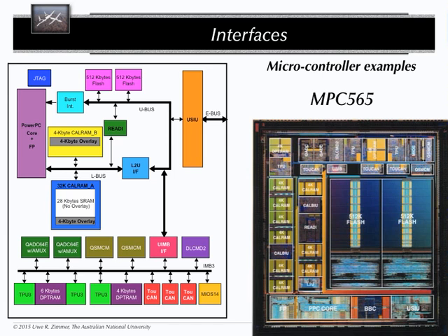Look at the rest of the devices which I have scattered around that one. Of course, a megabyte of flash memory is already most of the chip. And the decoder logic, just for the memory, is much larger than the whole CPU. It's interesting. Left of the PowerPC core, you have the floating point unit. Floating point units are quite large in comparison. That's the reason why in early microcontrollers you never had a floating point unit. And these early microcontrollers were so slow that you weren't thinking about floating point processing to start with.